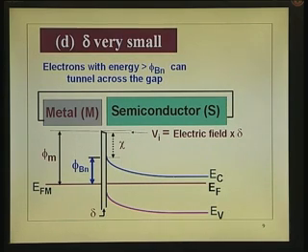further reduced. Now, you can see the entire drop is in the semiconductor, and the drop here is very, very small. So, if I have electrons here up to this point here, there is a possibility that they can cross this when it is thin, because when the oxide becomes very thin, and if there are states available on the other side, which actually is present here, this is the conduction band of the semiconductor, electrons can cross if they have enough energy. So, there is a chance for that to flow.